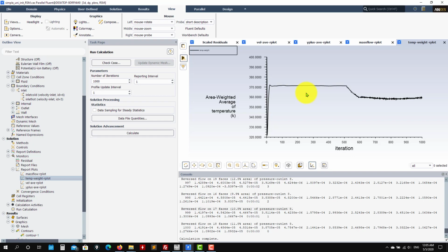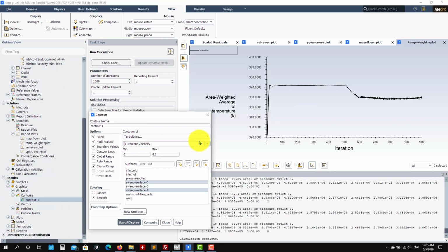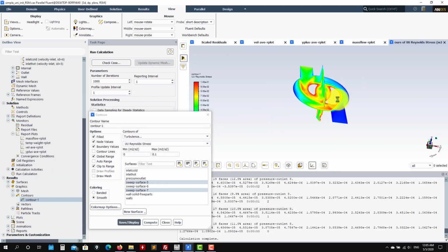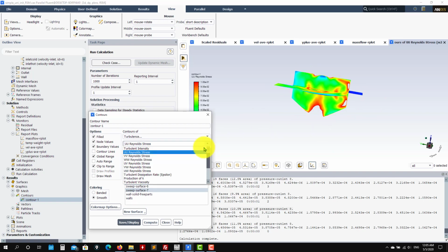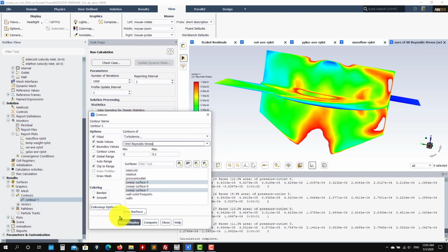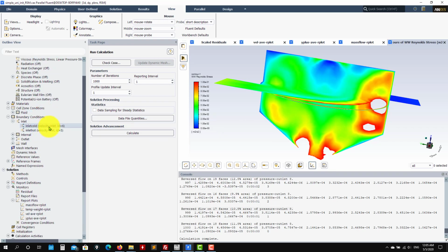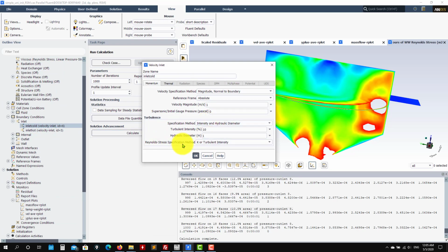And when you post-process these solvers, just also look at the Reynolds stresses, okay? So as you go here, you plot those values in Turbulence, so you will have all your stresses. These are the quantities that you are going to plot. And just to remind you, when you set boundary conditions, you have two ways to set it. You can use the K and turbulence intensity specification.